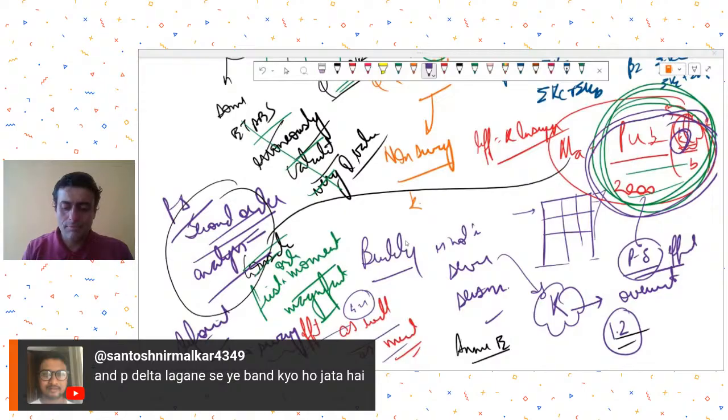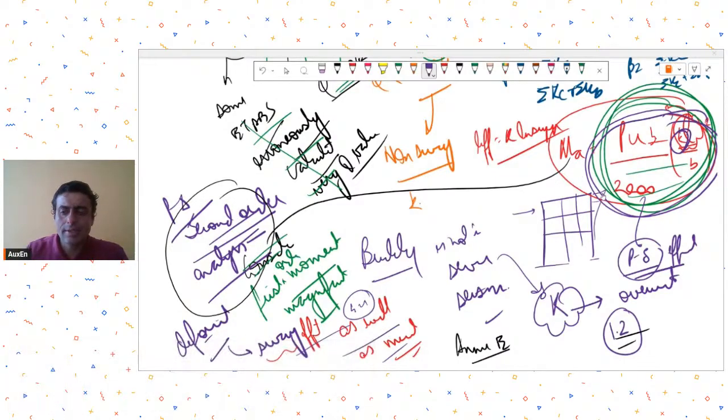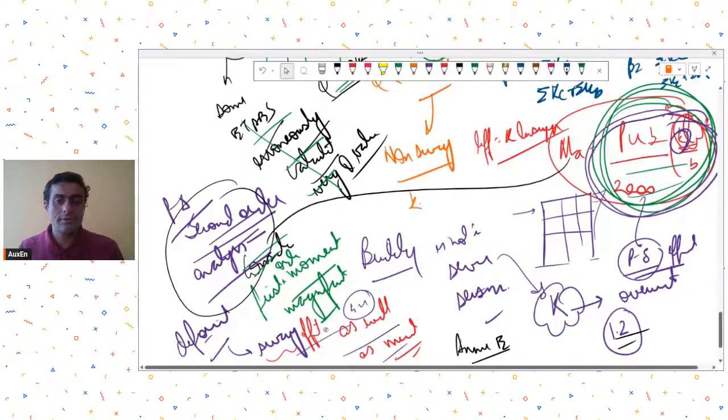So if you read the ETABS manual also, it says that the software, sorry, the code, expects that as a user you run the P delta, and when you run the P delta, the K value will be taken as 1, and then you just need to consider this additional moment formula for the P small delta effect. Okay. All right. So I think this question has been answered.